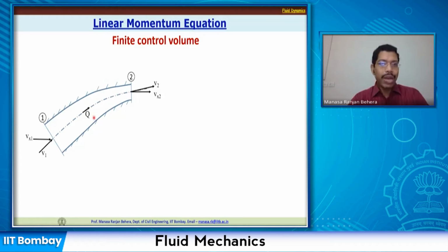If you want to calculate q at two different places, you can do that, which is nothing but area multiplied by velocity. So if you take this area and velocity v1, you will get the same q which is obtained by taking this area and this velocity v2. So q is not going to change, the discharge is going to remain the same because it is incompressible flow, right?